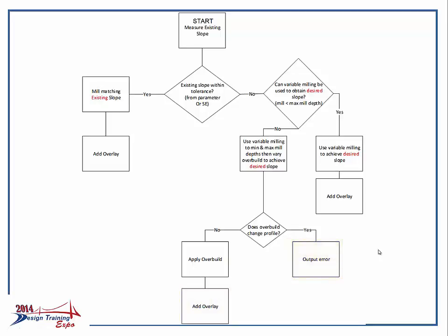error. In each case, we're going to see, as the subassembly gets inserted, a report of the performance of the subassembly is output that the user can see all of the resulting elevations, depths, areas, thicknesses, and so forth. And that information is output into a comma-separated values file that can be loaded into the plans or manipulated with spreadsheet software such as Microsoft Excel.